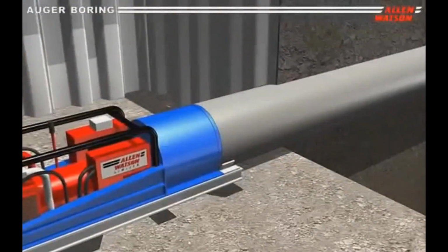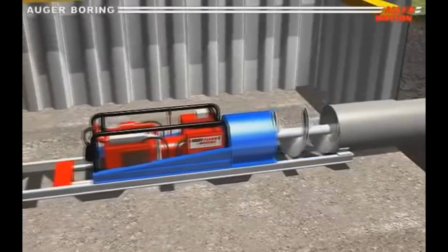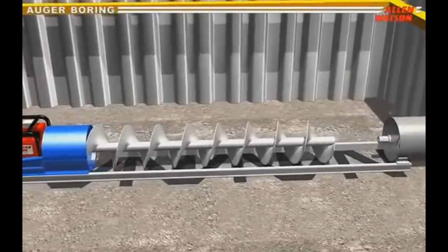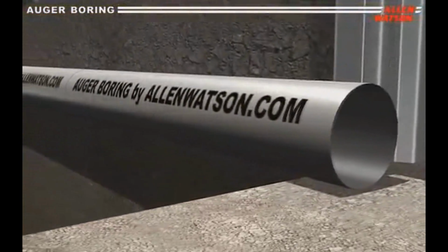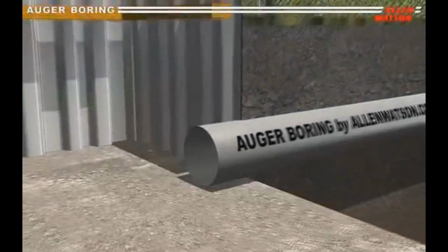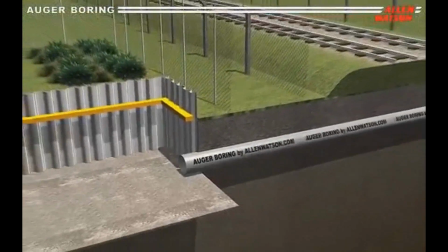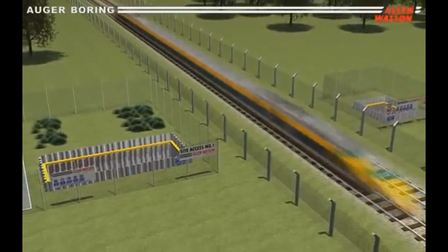Where the 2 times width is not practical as, say, for a 1-story warehouse or a department store, boring depths of 6 to 15 meters may be adequate. On the other hand, for important or high-rise structures that have small plan dimensions, it is common to extend 1 or more of the borings to bedrock or to competent soil regardless of depth.